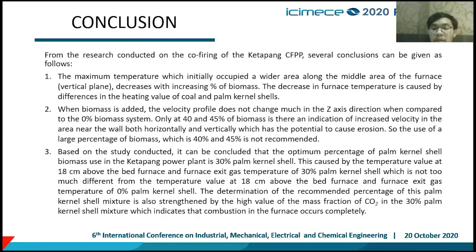So the determination of the recommended percentage of this palm kernel shell mixture is also strengthened by the high value of mass fraction of carbon dioxide in the 30% palm kernel shell mixture, which can indicate that combustion in the furnace occurs completely.